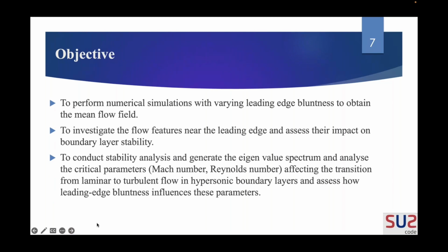The main objective is to perform the numerical simulation for the sharp leading edge as well as the blunt leading edge radius, and to also focus on the flow physics and to study the stability parameters. Here I've considered around 5 cases, the sharp leading edge case and 4 blunt leading edge cases with varying nose radius from 10 micrometer to 1000 micrometer.